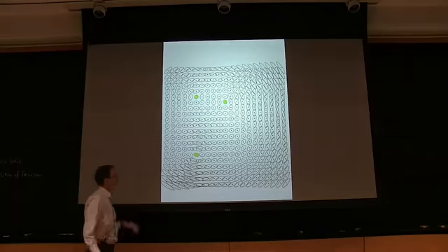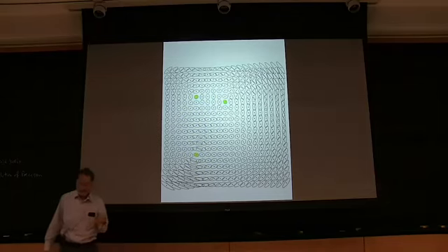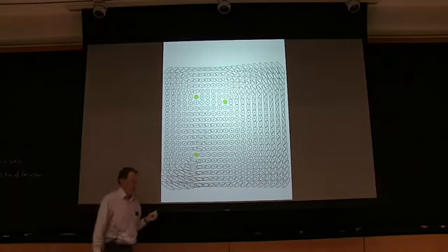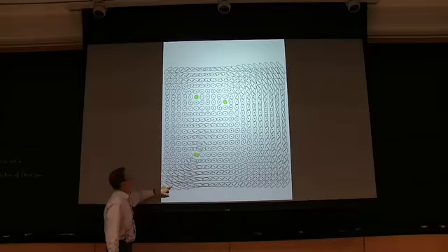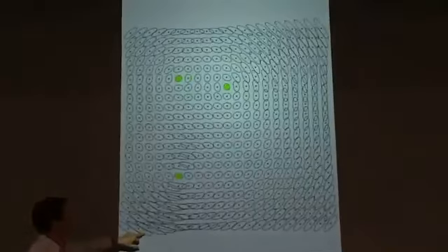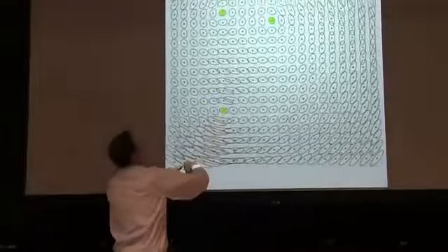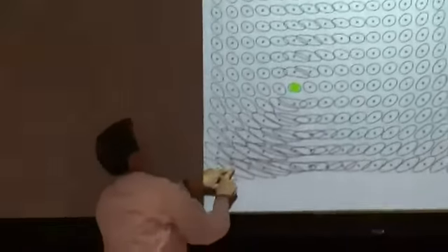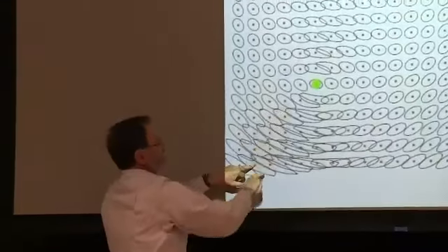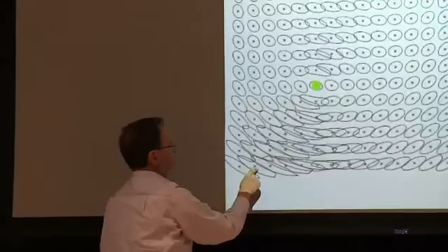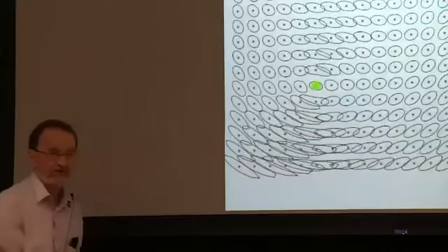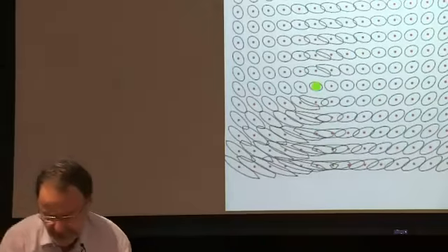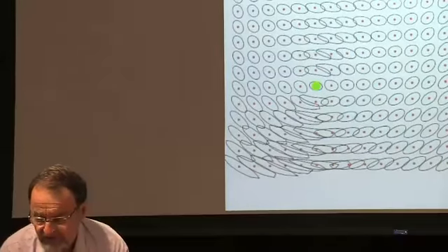At the same time, we can show that if you put them in a line, that's a really bad idea. And of course, that's what they are here, everywhere. Again, the idea here is that if I'm over here and I move a little bit to the side, I'm not changing the distance to those 3 responders much, because I'm moving pretty much at right angles to those 3 vectors. Therefore, I won't really notice that I've moved. And conversely, I can't determine my position in that direction as well. So that's with 3, and let's go one more.